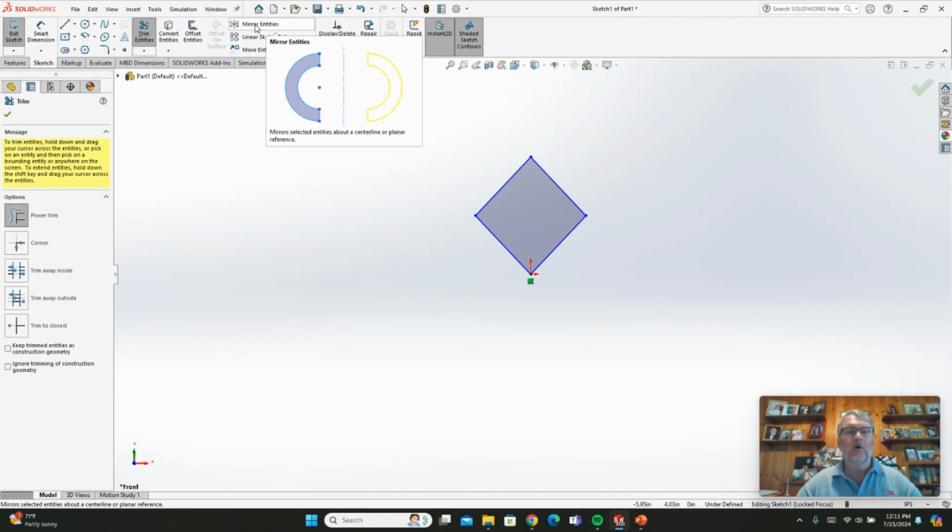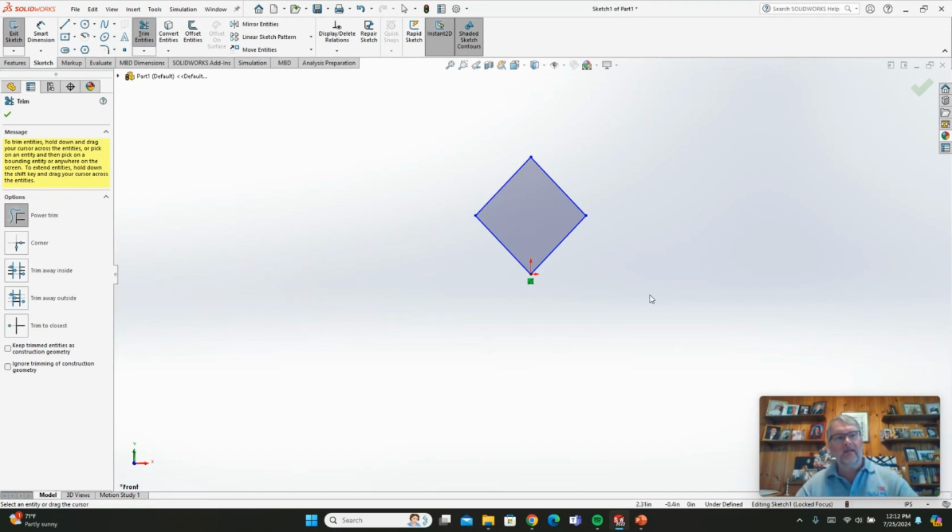What you need to be careful of, though, is when you do mirror something. For instance, in this little picture you see right here, you can actually put a line out a ways and mirror around that, so they're not connected. I did something that was connected, but you can't. The mirrors can't intersect. So I couldn't take half of that. For instance, I couldn't do this piece right here. I couldn't mirror around that right there. So when they mirror, they can't intersect. So that's just important to know.